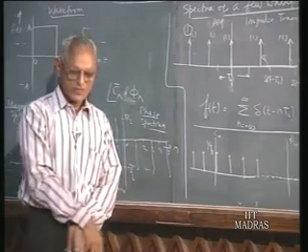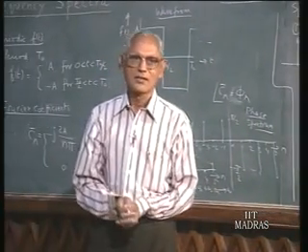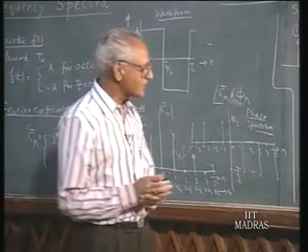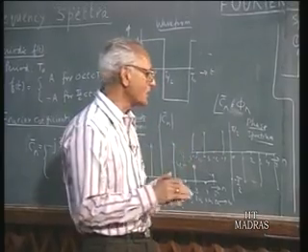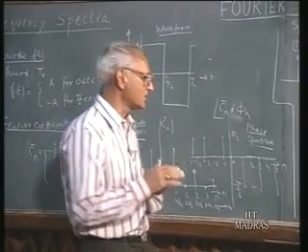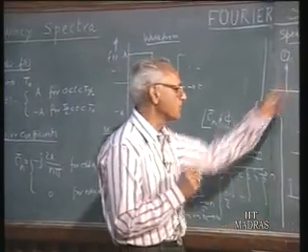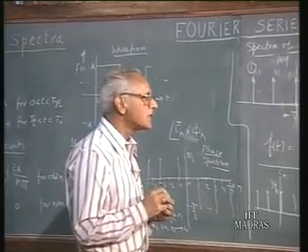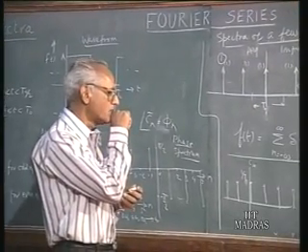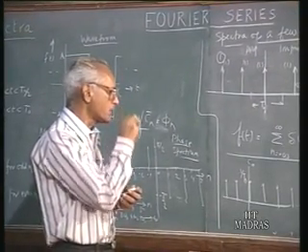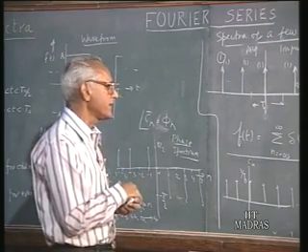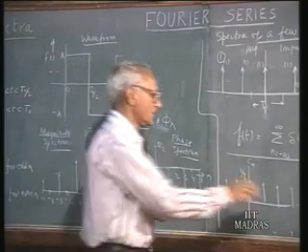That means all frequencies, that means we can say a train of impulses is, so to say, impartial to the order of the harmonic. All harmonics of equal strength go together to compose this impulse train. This is quite an important fact. This particular property occurs again and again in our future discussions.